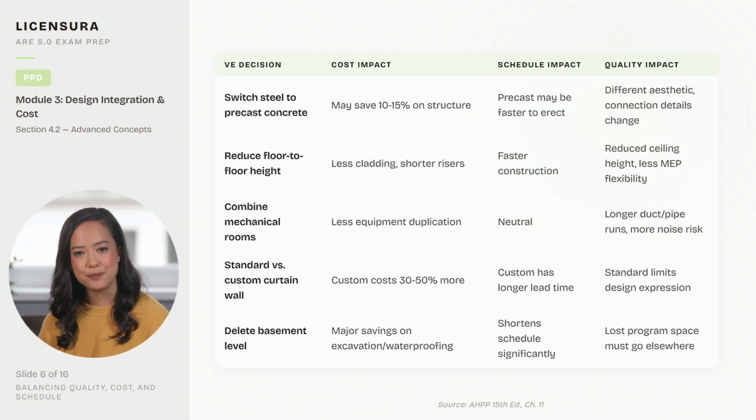Shelf angles supporting masonry must accommodate structural deflection, typically limited to span divided by 600. Window and curtain wall anchors must be coordinated with the structural frame for proper load transfer. Expansion joints in cladding must align with structural expansion joints, and flashing and drainage must be detailed at every floor line and opening.